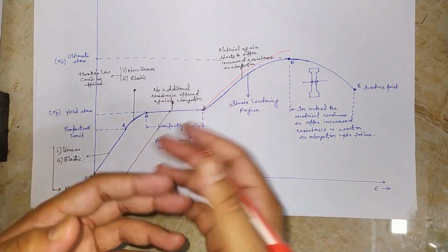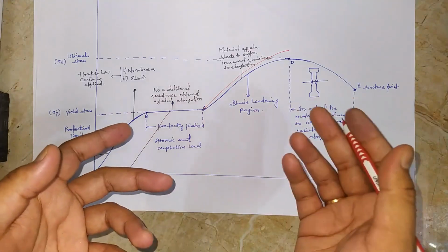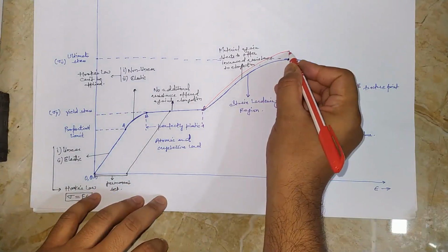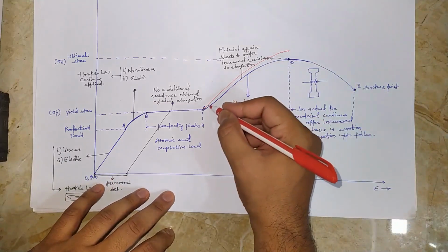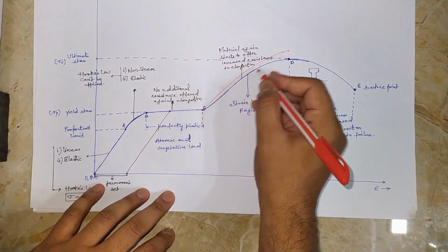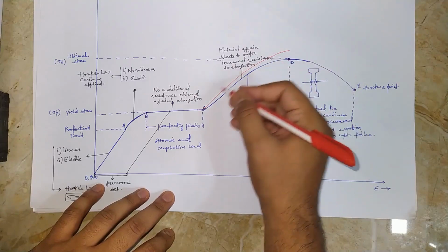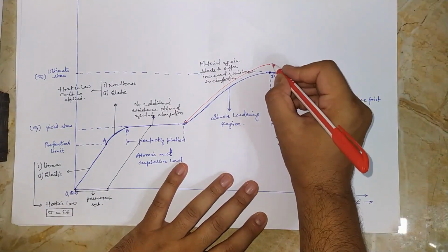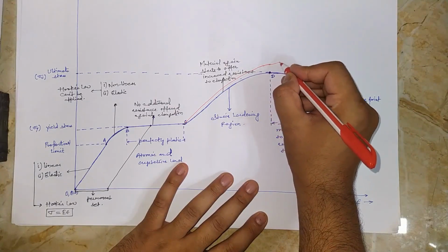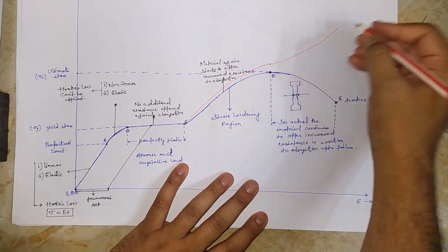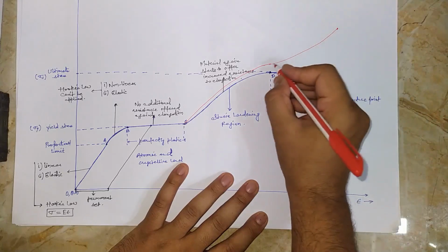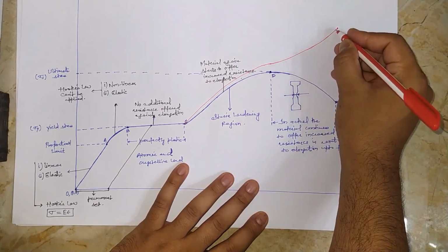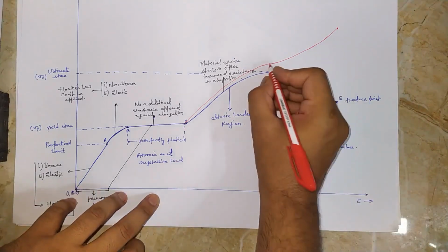Although it is difficult to determine at each point, if somehow by devising a method we can do it, we can draw the stress strain diagram. So it slightly tries to dissociate itself from the nominal stress strain diagram during the stretch from C to D, but you will be amazed to see that between D to E it completely dissociates from the nominal stress strain diagram and goes on an opposite slope, that is, a positive slope.